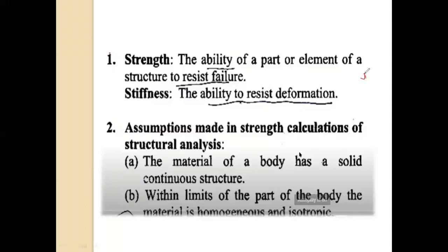Suppose this is our cube, 15 centimeter by 15 centimeter by 15 centimeter, a 3D block, and you have to perform a compressive test. So strength means you have to check the load carrying capacity of this block without failure. So this is called strength.